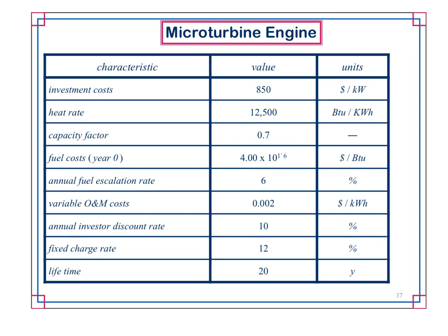I'm not exactly sure what happened to the printing, but fuel costs should be 4 times 10 to the minus 6 dollars per BTU. I don't know why that got a little weird like that, but it's $4 per MMBTU, 4 times 10 to the minus 6 dollars per BTU. Our escalation rate is 6%, and our variable O&M cost is about, again, this is a nameplate number, so we can make the calculations easier, 0.2 cents per kilowatt hour. Our discount rate is 10%.